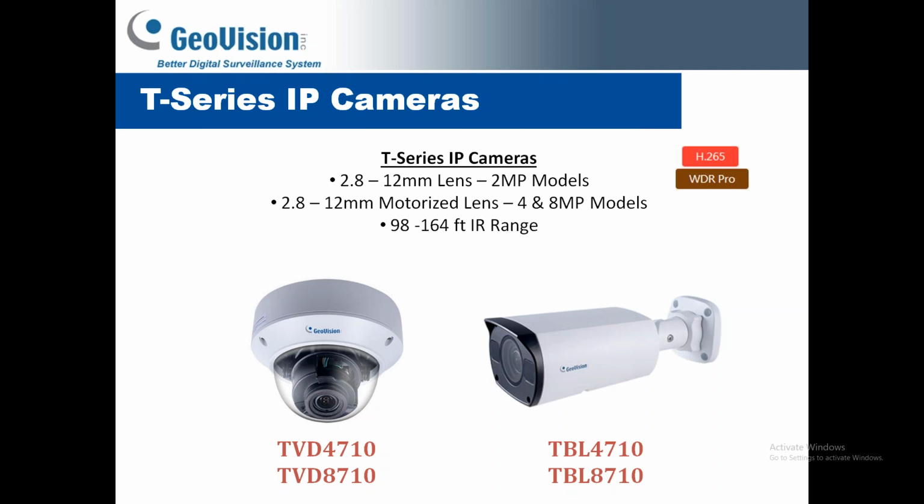Another thing that I do want to point out, we've started doing new on our dome style cameras. It has a new style IR LED where it's a single LED instead of multiple bulbs. What this does for you is it gives you a much better night viewing capability. In most manufacturers' domes that have integrated IR, you used to see somewhat of a halo or an IR glare effect. With these new domes, you have a single LED, and you've seen quite a bit of reduction in any IR bounce back.